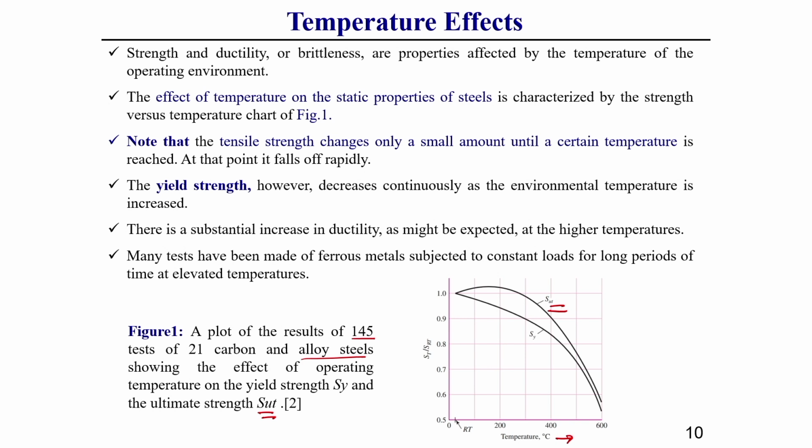So, you need to consider either the Kd polynomial equation, or you can use Kd as the ratio of St, that means the ultimate strength at a particular temperature, by the ultimate strength at room temperature. That ratio you can also use for the Kd calculation.